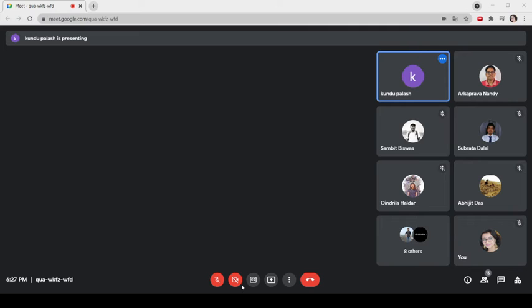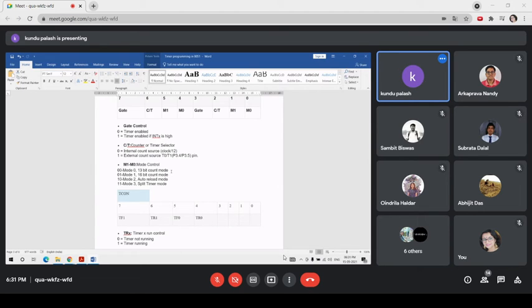So what is the timer? Simplest is that mode 0 means the timer can be operated with a 13-bit mode of operation. So what will be the maximum value of 13-bit in binary? Can you calculate? 13-bit, compared to 16-bit, means 3 extra bits. So the most significant 3 extra bits will not be considered.